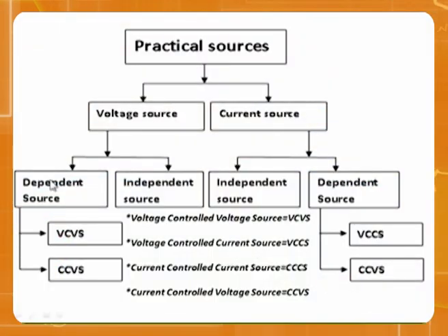Suppose the sun has become dark, the moon automatically becomes dark. So if the independent source is 0, the dependent source automatically becomes 0. That's how you need to understand. Therefore, never say a dependent source is a source. It's not a source. The very reason it is depending, it's not a source.